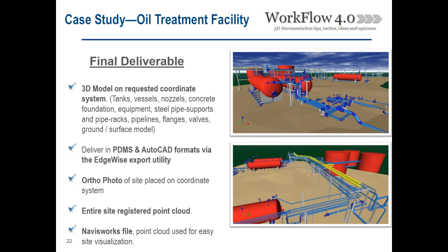We also delivered the orthophoto on the coordinate system, which we actually did in Faro Scene software. It has a way to take the point cloud and clean it up and give you a top view and make an accurate orthophoto, which we could then bring into AutoCAD and place on the coordinate system and really use it like it's an aerial photo with accurate measurements.